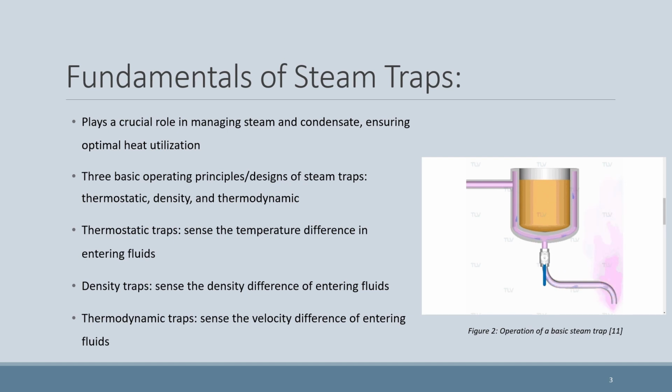To properly sense the different variables in entering fluids, there are three basic operating principles or designs of steam traps, being thermostatic, density, and thermodynamic. These three sense the differences in temperature, density, and velocity of entering fluids.